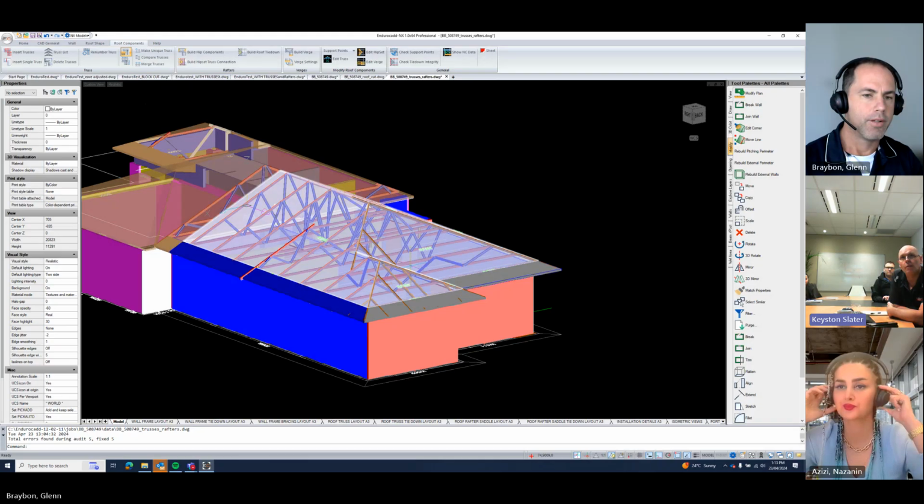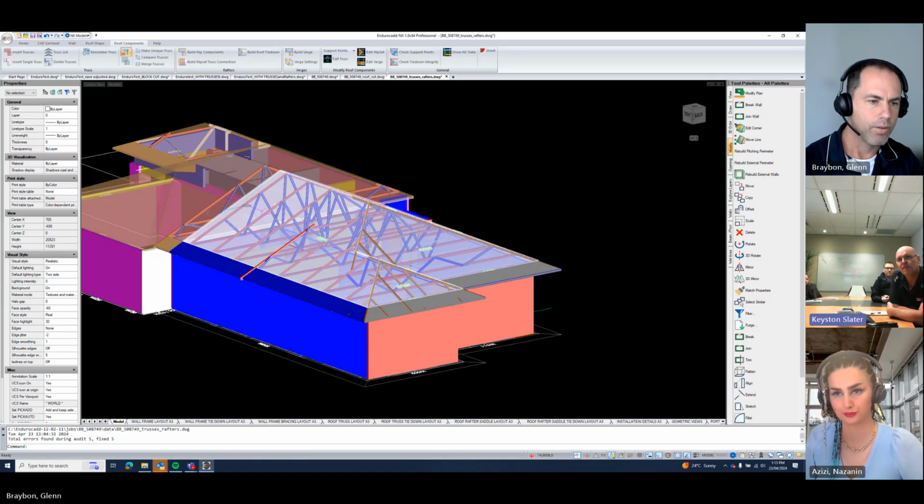I know you can turn the wall other off as a layer, but sometimes I use a beam other for a beam that might be a fabricated beam, just so it's showing up on there, and we can then renumber that while it's still visible, unlike the wall other. That's all. Yeah. Yep. Minor things.